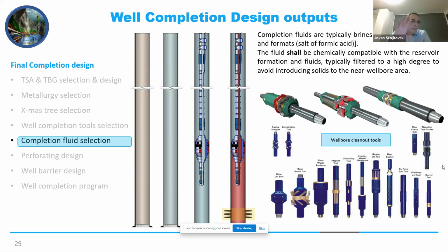And then in the same run, we can exchange the fluid with the completion fluid, which, by the way, also has a feature that it will not interact with the reservoir after we perforate the well, because after we perforate, this fluid will be exposed to your reservoir. So you don't want to have any emulsion or any bridges which will decrease your production rate, which you estimated.